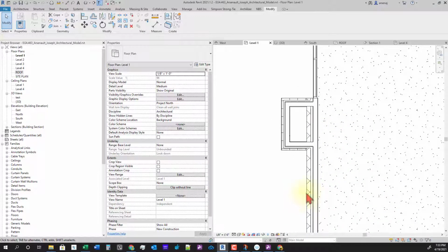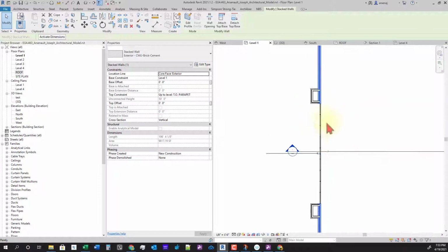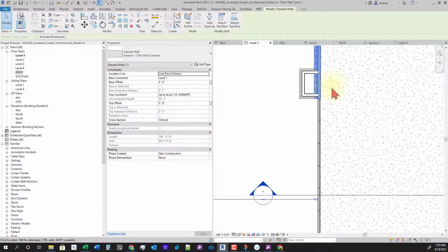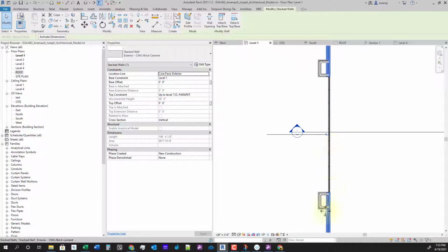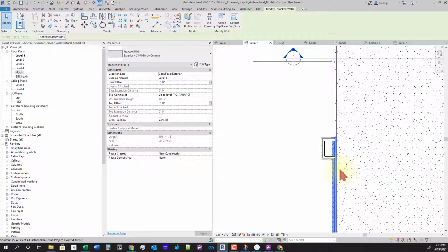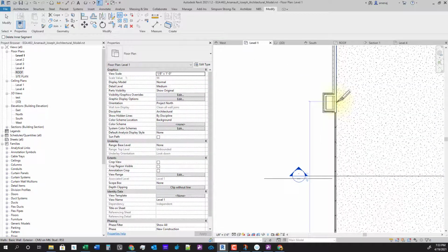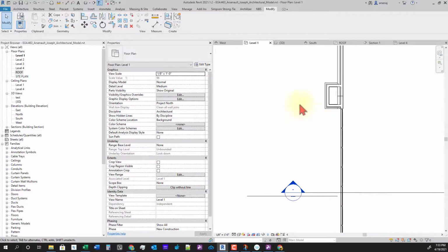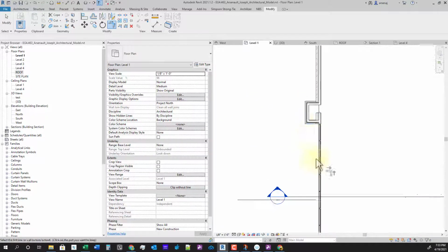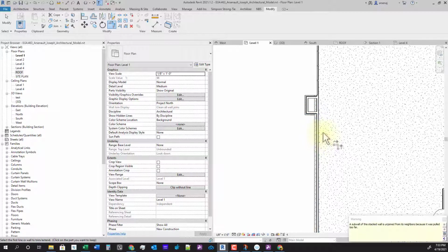I'm going to split this wall because we don't need this wall that this curtain wall is on to be exterior. We don't need it to be the brick wall. So let's slice. You can type SL or come up to the Modify tab. And over here you can split element. It's on the Modify tab right next to the mirror, by drawing an axis split. And we'll split this wall here, and split it here on this side. And TR to trim.